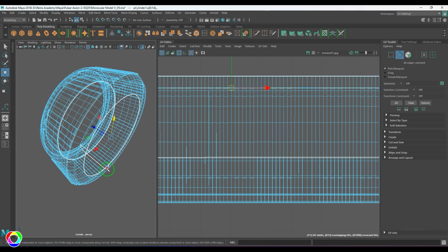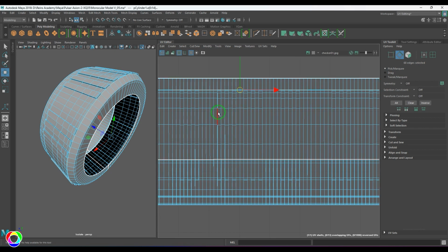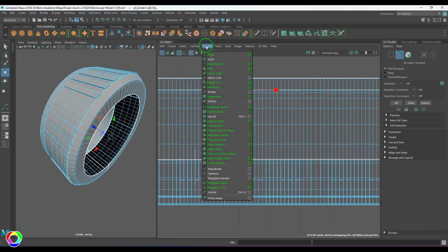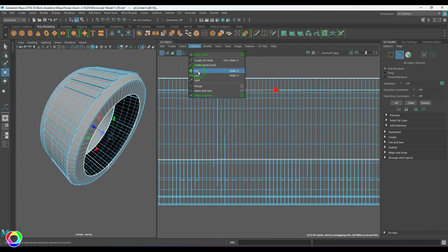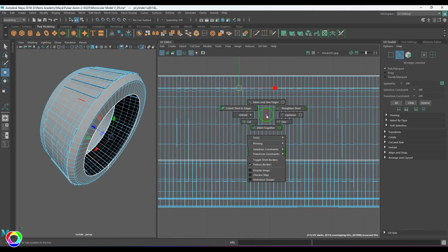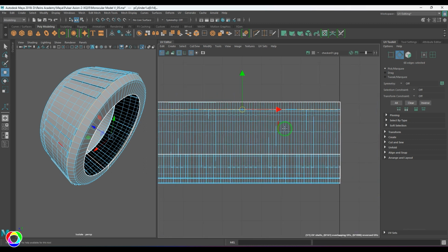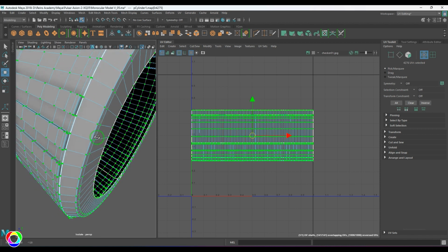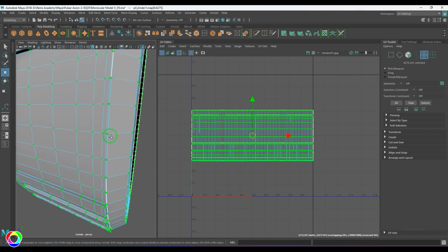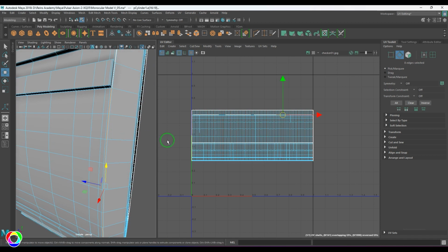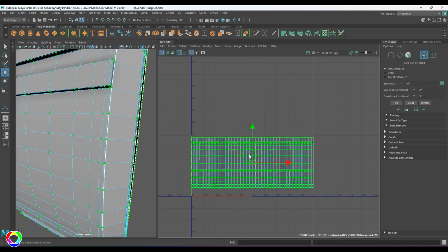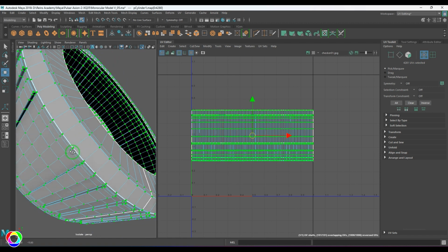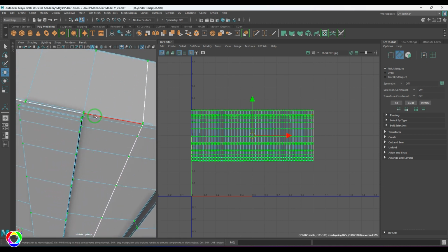So I've selected them. Now I'm going to use the cut UVs tool. I can go to the tools here and then search for the cut UV tool. Okay, so it is Shift X, the keyboard shortcut, or you can hold Shift, right click and then search for the cut tool, and then you should be able to separate that line. When it is not separated, it means I might have not selected a few of the lines there. So I need to constantly check with that. Somewhere this line has not been selected.